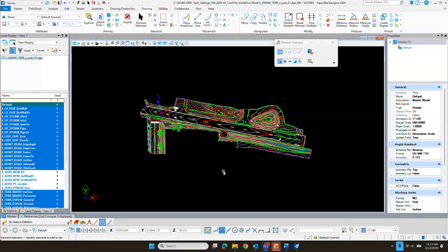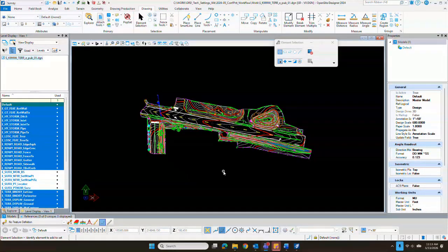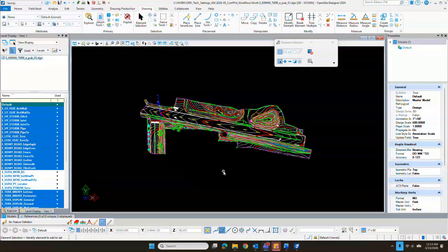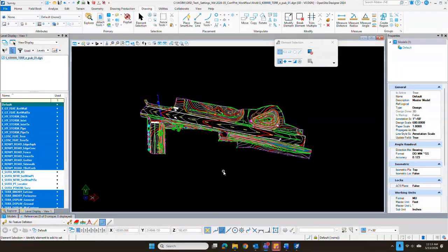Confidence points are something that is primarily a survey function, but sometimes other disciplines need to do them. We need to do them at survey handoff to construction to make sure our terrains are still active, true, that the world hasn't changed underneath what we mapped when we started the project.